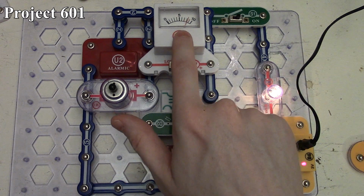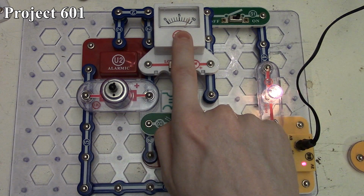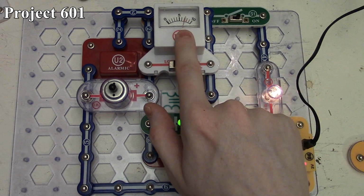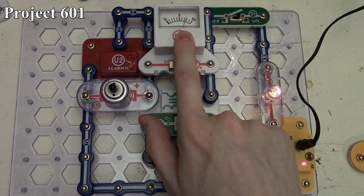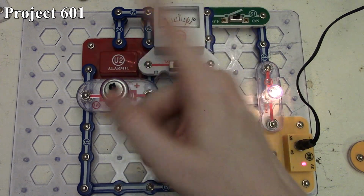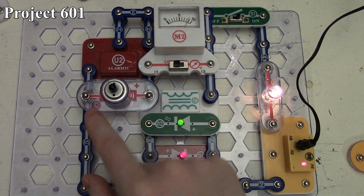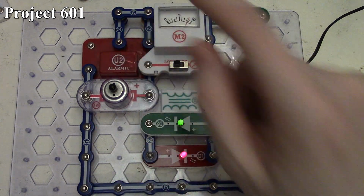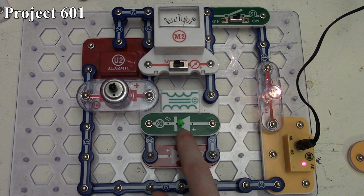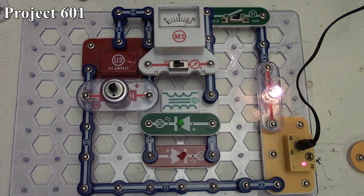And we can see that being reflected on our meter here, both the alarm IC and also the AC voltage being generated by our motor here. So we can see the meter deflecting some, but it's also, of course, not deflecting all the way back because the motor free spins when the alarm IC turns off momentarily, and that's how we still get some output here on our transformer.